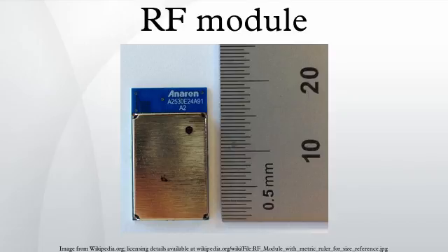In addition, reliable RF communication circuit requires careful monitoring of the manufacturing process to ensure that the RF performance is not adversely affected. Finally, radio circuits are usually subject to limits on radiated emissions, and require conformance testing and certification by a standardization organization such as ETSI or the U.S. Federal Communications Commission. For these reasons, design engineers will often design a circuit for an application which requires radio communication and then drop in a pre-made radio module rather than attempt a discrete design, saving time and money on development.